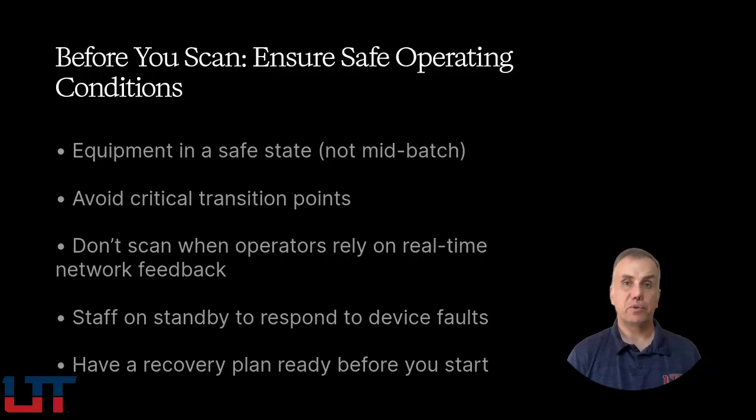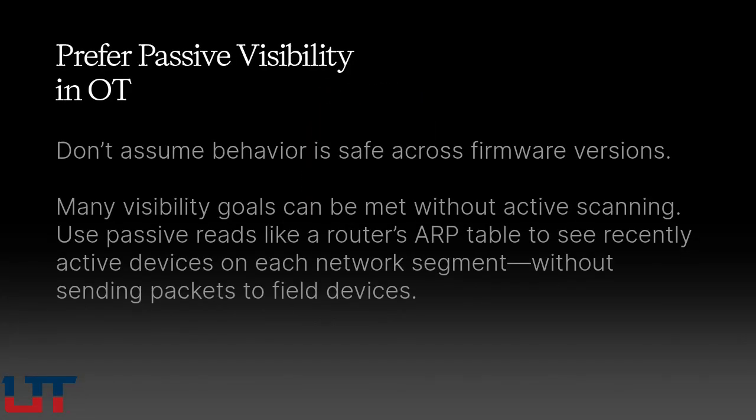A recovery plan before you start. Know the procedure for recovering a faulted PLC, an unresponsive switch, and a crashed HMI. Have the relevant passwords, recovery procedures, and vendor phone numbers ready before any tool runs. Lab testing first, with the same device models and firmware versions as the production environment, if at all possible. Behavior that's safe on a new firmware version may not be safe on the firmware running in production. Don't assume.